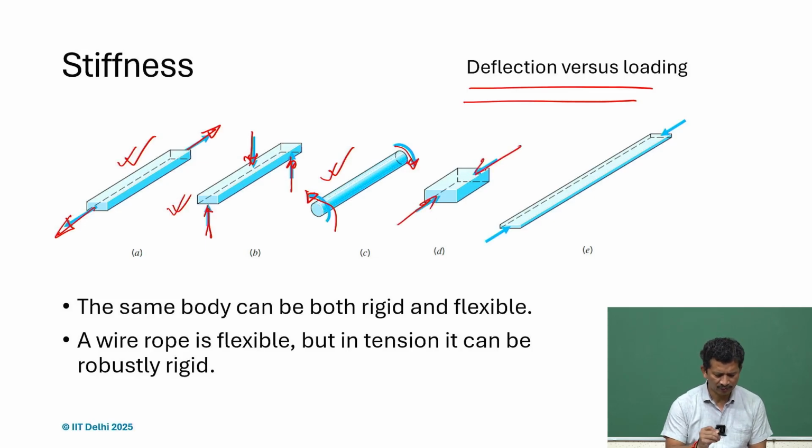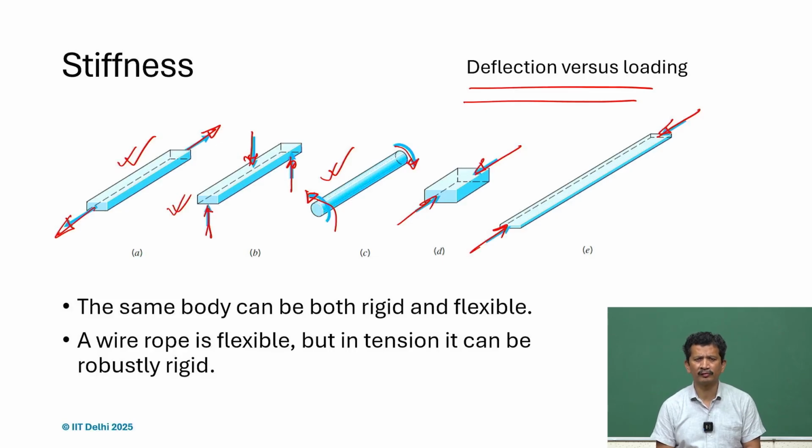We can also have axial loading, but in compression. So, a smaller bar, it can be a very thin structure undergoing compression. Under tension we may not have a problem, but for the same longitudinal member under axial compression, if the cross sections are very small, what we call slender, and we talk about the slenderness ratio in design, we also face problems with stability, and we have to take care of buckling, or warping in 2D cases. So, that is something we also need to understand.